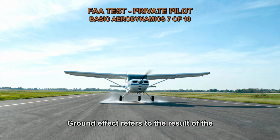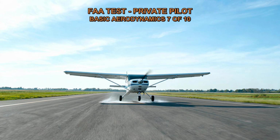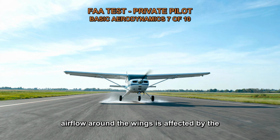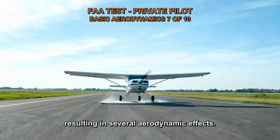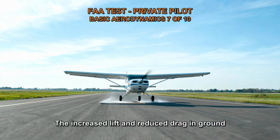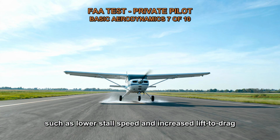Ground effect refers to the result of the interference of the surface of the Earth with the airflow patterns about an airplane. When an aircraft is flying close to the ground, typically within one wingspan or less, the airflow around the wings is affected by the presence of the ground. This interference causes changes in the airflow patterns, resulting in several aerodynamic effects. These effects include an increase in lift, a reduction in induced drag, and a decrease in wingtip vortices. The increased lift and reduced drag in ground effect allow the aircraft to experience improved performance, such as lower stall speed and increased lift-to-drag ratio.